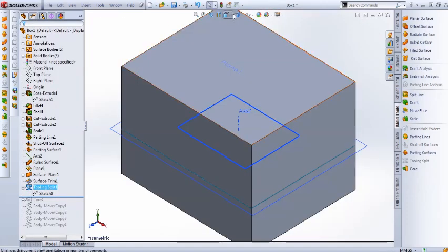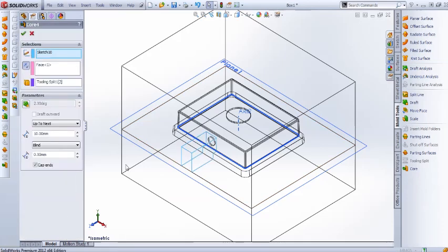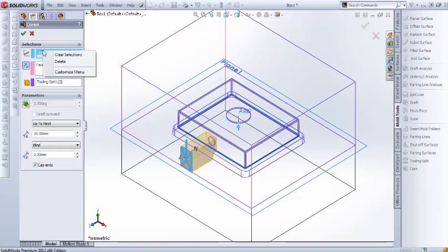Now the next task is to see how the parts are built after this operation. Now the cavity core needs to be created. The cavity core is created in such a way that you select that plane and draw a sketch, and once the sketch is drawn and you select up to next, the core will be selected.